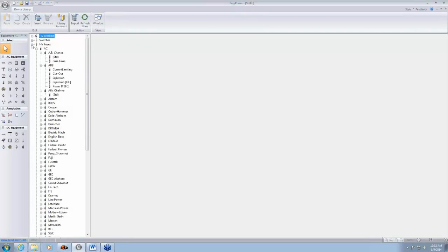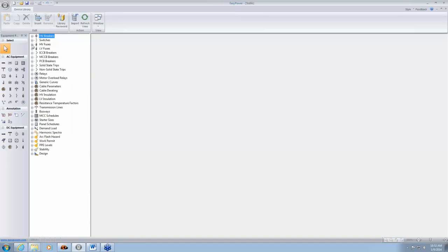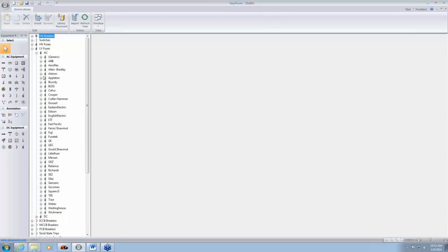So if you want to add any types of new fuses on your own, you can do that. If you want us to do that, we can add any type of fuse that you're looking for. We have some engineers here continually adding to the predictive device library, and this has grown rapidly over the last few years based on demand from the users. So low voltage fuses, we've got different varieties there. If you were using Bussmann or Ferraz Shawmut or whatever, they're all there.